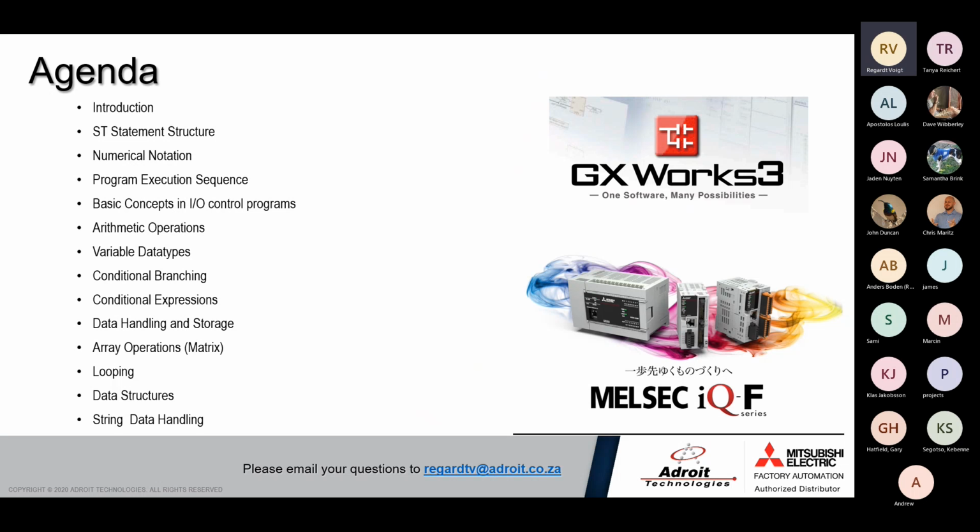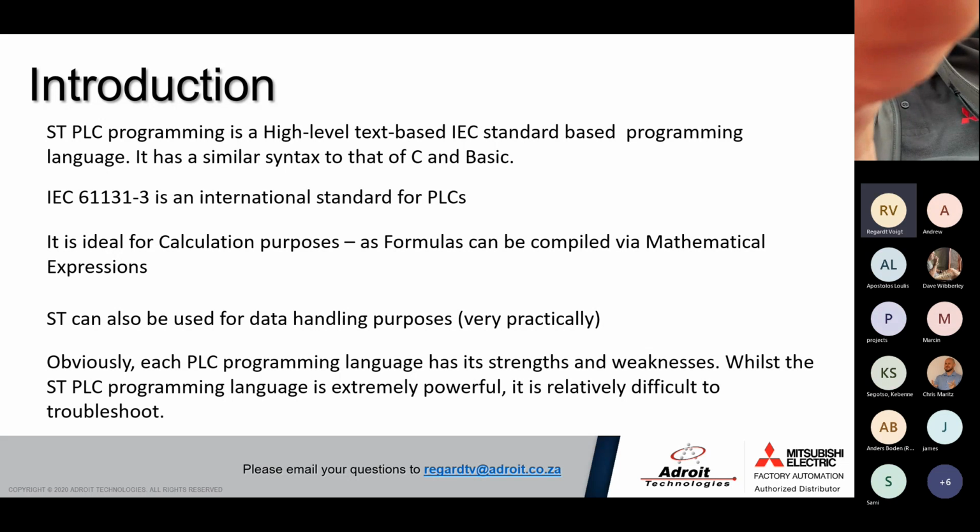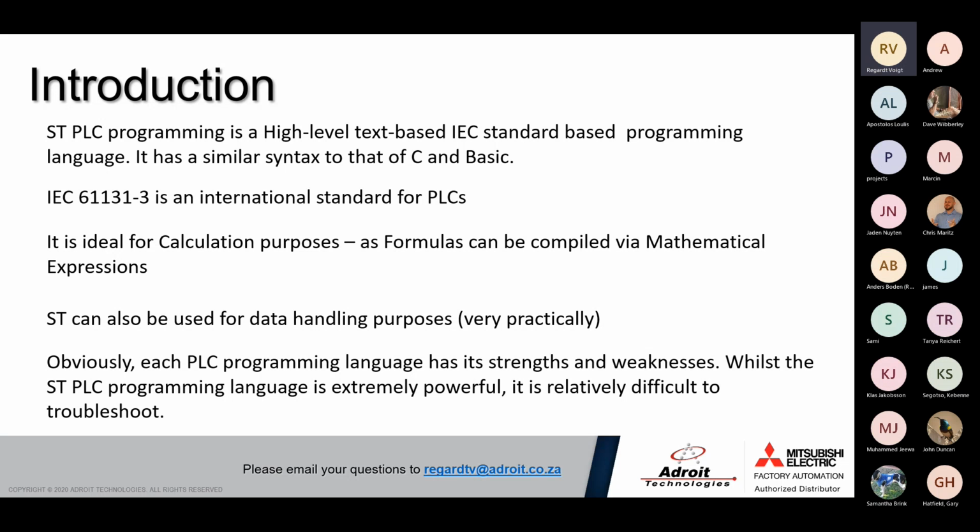If you look at the structured text PLC programming language, it's a high-level text-based IEC standard programming language. By high level, I mean it's leaning more to the text-based, not so much the visual aspect like sequential flowcharts, ladder diagrams, and function blocks.